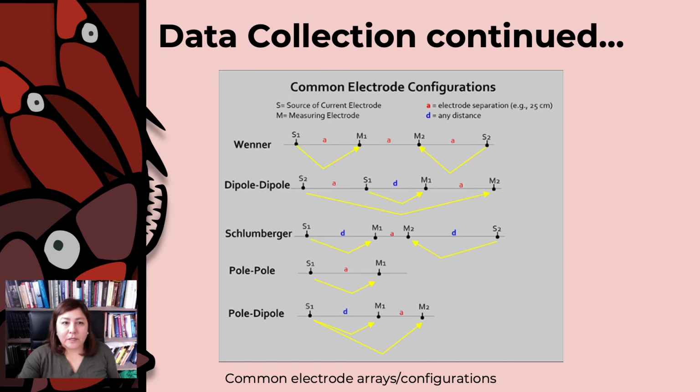For area surveys, grids are established over the area of investigation in much the same way as for GPR survey. For the GeoScan RM15, 2 pairs of probes are used, usually configured in a twin probe array. The first mobile pair of probes are attached to a frame and are moved systematically across a survey area. Also connected to the frame by a 50-meter cable is a second remote pair of probes that are left in a stationary position to record background resistance.